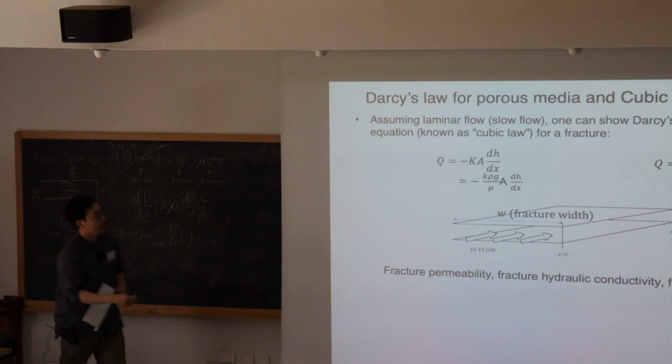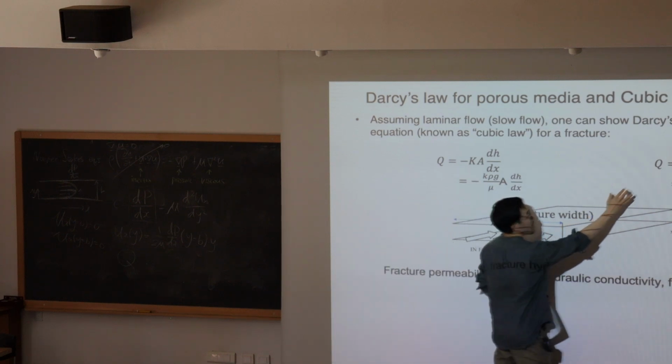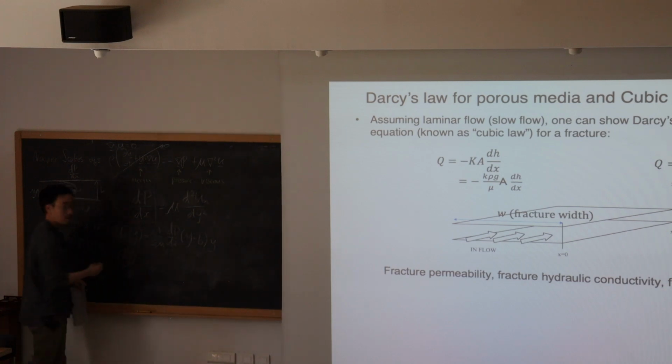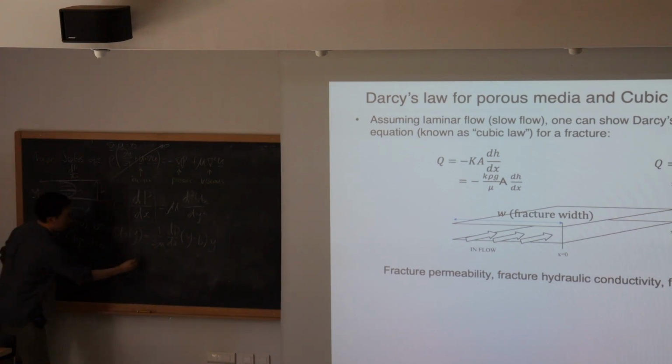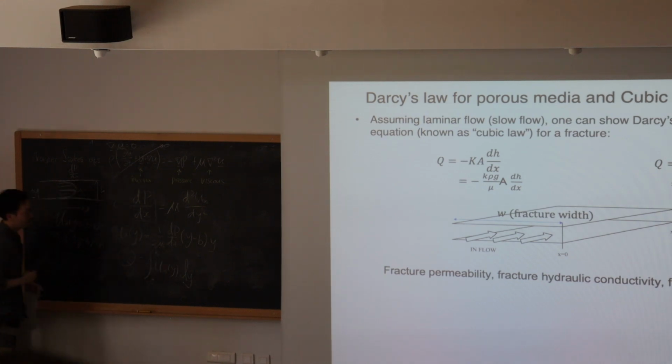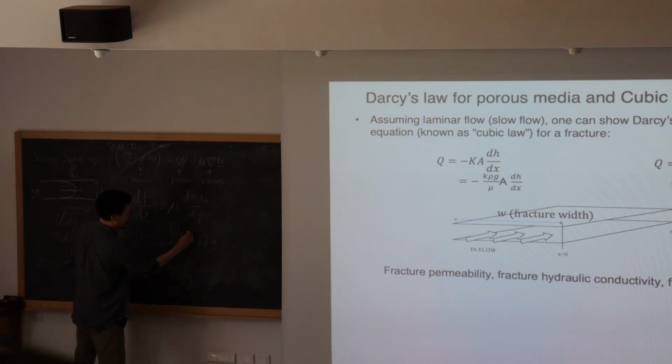So how do we go from ux to q? That's our objective, right? We want to express q, the volumetric flow rate. So how do we go from u to q? Yeah, we integrate u of x in the y direction. You just integrate from 0 to b. Do you see the cubic appearing? You have this y squared times y. If you integrate once, it is y cubed, and if you plug in b and 0, it's as simple as that.